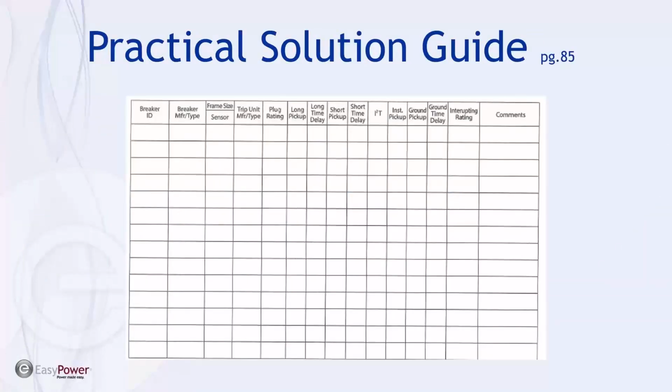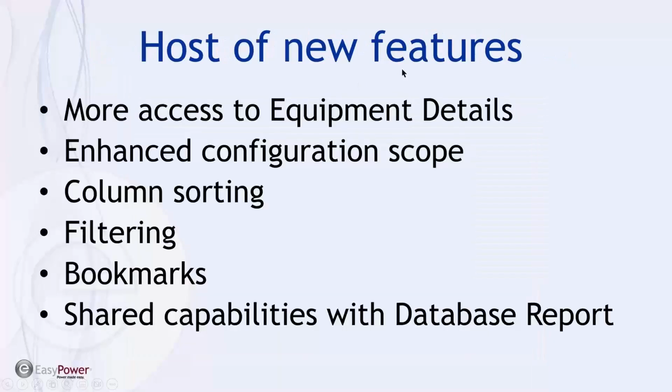Now, in terms of data collection, this is a reprint of page 85 of the Practical Solution Guide for collecting data on breakers. My recommendation has always been to utilize the database browser to make up your own spreadsheet for each type of element, and depending upon what your process is, incorporate that into doing the data collection.